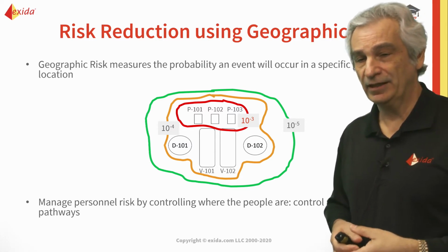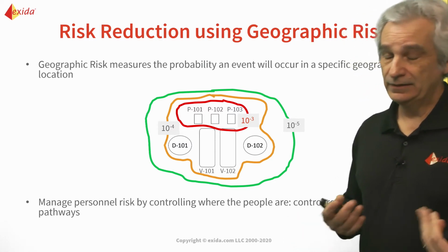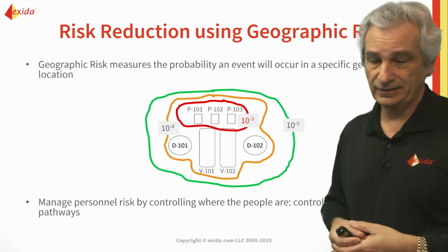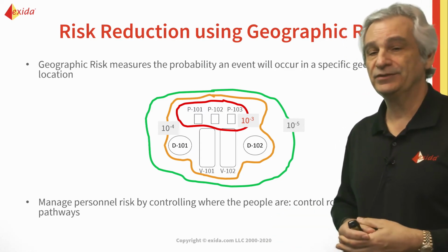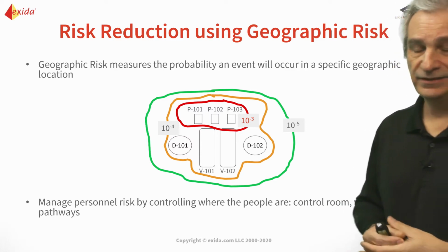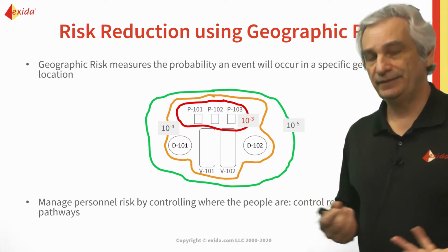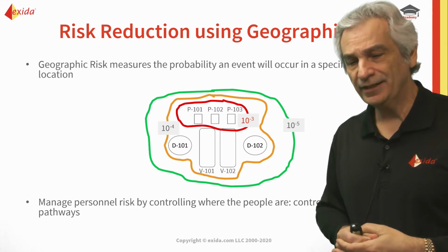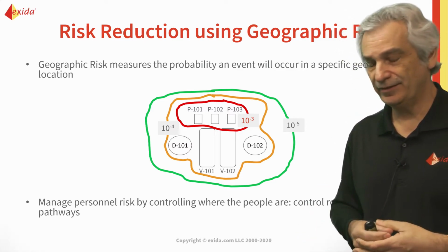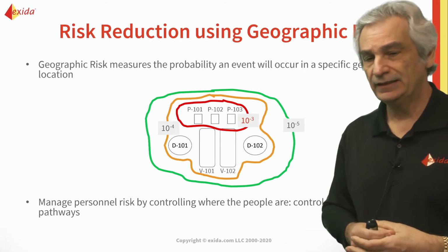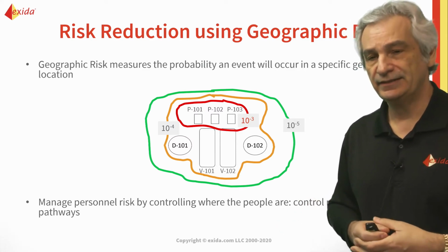And so a blast wave, and again, a lot of companies do use QRA, another acronym, quantitative risk assessment. This is where they will employ somebody to come in and do some modeling. They might do some blast wave modeling, they might do some cloud dispersion modeling. They'll look at all of this and take it into consideration.